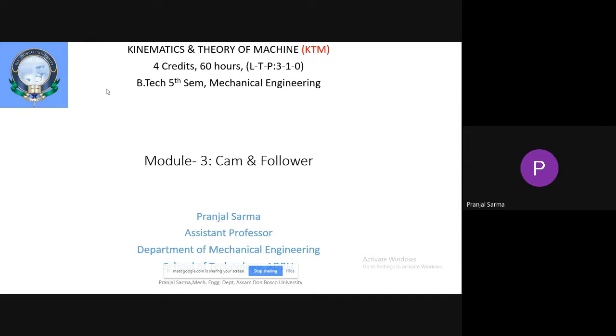by checking what kind of joint it is, binary, ternary, etc. Utilizing the concept that a binary joint gives you one equivalent single pair, and a ternary or any higher order joint gives rise to, suppose n links are joined at that particular connection, then n minus 1 equivalent pairs. So those things you have to utilize. Now any more doubt, anyone, any question? If no, we'll move on.